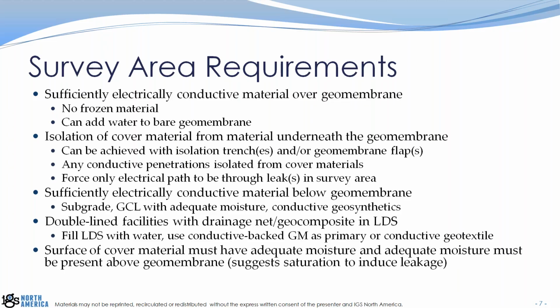Actually, I'll go back to a conversation I recently had with a friend of mine, and he said, I have a pond. It's a bare liner. What's the best bare liner testing method to perform on this pond? And I said, well, the water-based, like water puddle method works better on the floor because there could be wrinkles. It works better on wrinkles. And our testing method works better on slopes. And he said, well, what about just filling it with water? And I said, actually, yeah, filling it with water is even better than those because it forces the leak to leak. If you're doing arc testing and you have a hole on a wrinkle, not likely to pick it up.